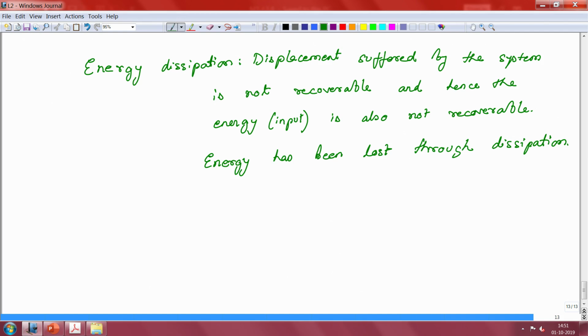So, there is a very interesting difference between a classical elastic solid and a classical viscous fluid in the energy sense. They are the extreme opposites. While the ideal classical elastic solid will store energy for you for an infinite amount of time, the classical viscous fluid will lose all the energy that you have put in; all of it is dissipated.